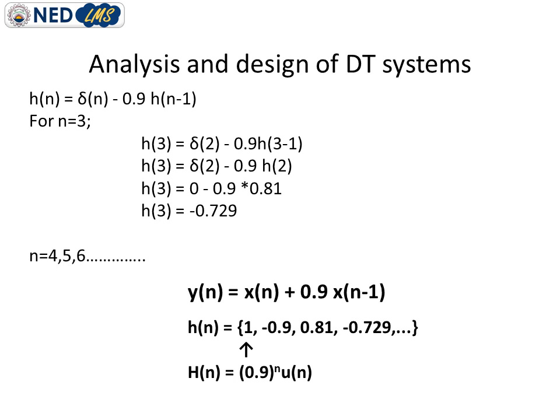And from these steps, you can easily understand that this impulse response is never ending. However, it is converging in nature, but as it depends upon the previous impulse response, and we obtained some magnitude in the previous step, there will be some magnitude obtained in the current step. So by this way we can conclude that this is the infinite impulse response, which we can also prove earlier by looking at the difference equation.